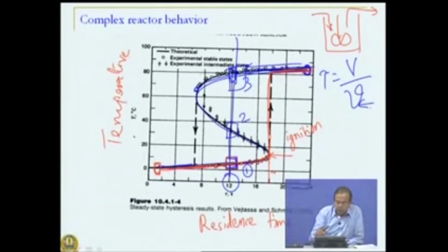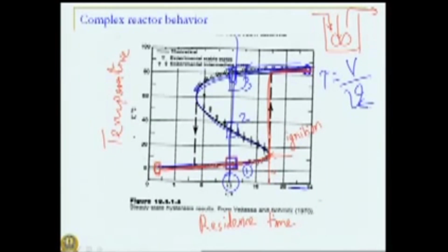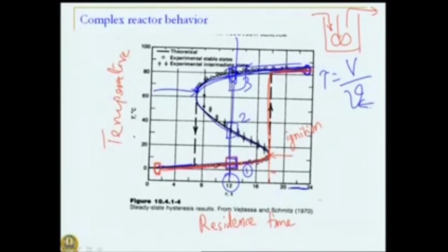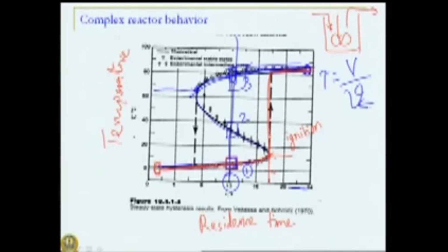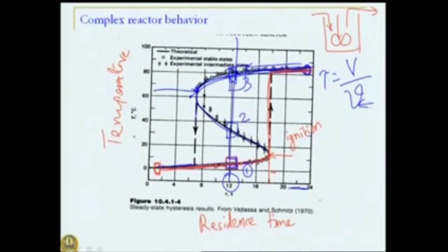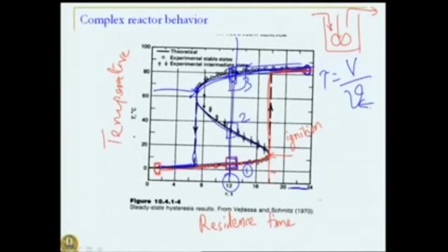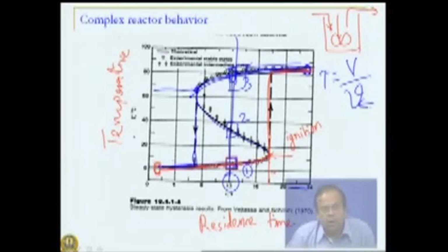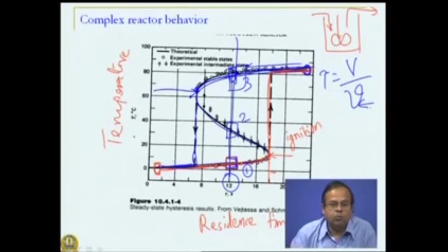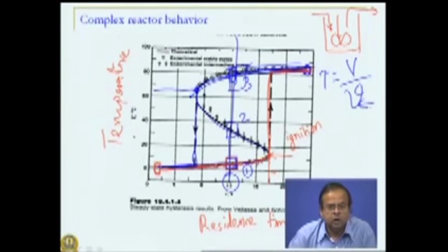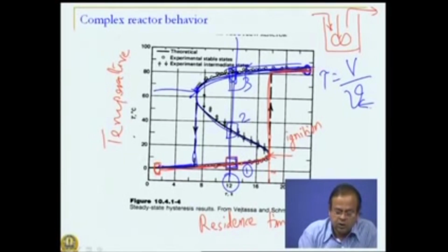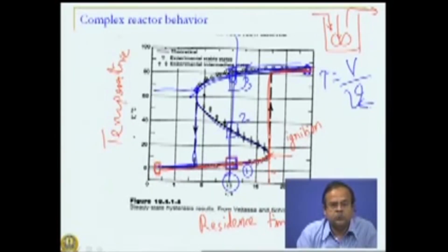Now, let us reverse the phenomenon. If we are coming from a high residence time, you are getting very high temperatures, but if you decrease the residence time marginally, you suddenly come to the lower branch, that means temperatures decrease suddenly. So, reverse of ignition: an ignited candle suddenly blown off or extinguished, and there is darkness. In our reactions, a high temperature suddenly becomes a low temperature scenario.